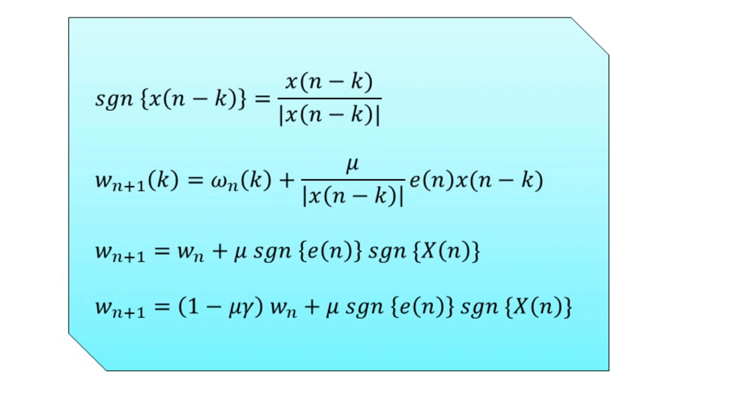Now we are going to have a brief discussion with respect to the third and the last type to be discussed. So that is the variable step size algorithms here. Now as we have seen in the mathematical expressions describing the LMS algorithm, there is the use of step size denoted by mu here for selecting the step size in the LMS algorithms.